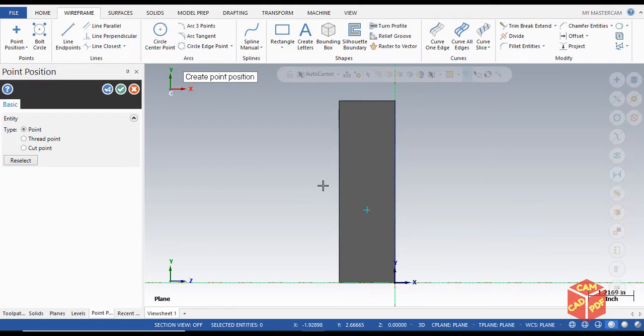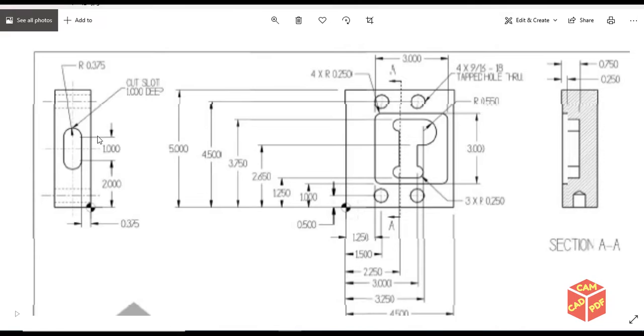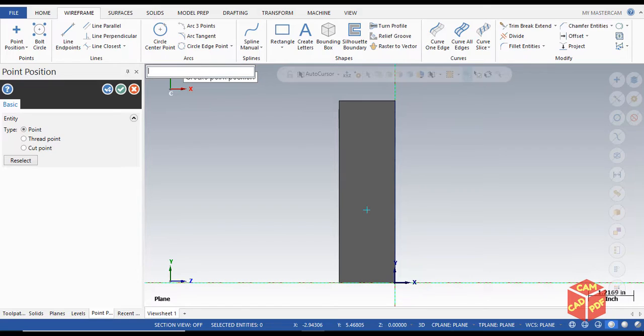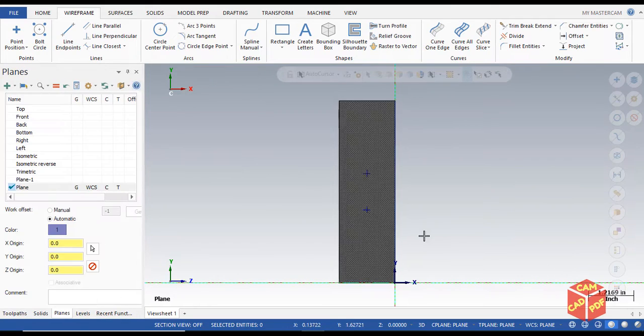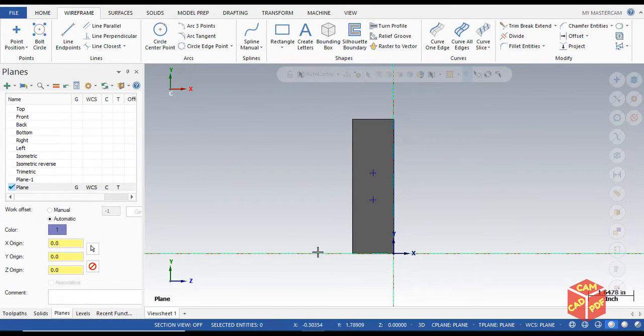So Mastercam detected it automatically, and now we're gonna create another point which is gonna be the same. Click on XYZ, and this time our height is gonna be 3 inches and our X similarly to what we did before. So negative, put brackets, 0.375 plus 0.375, then comma, 3 inches, hit enter, and now you can see we created our 2 points.